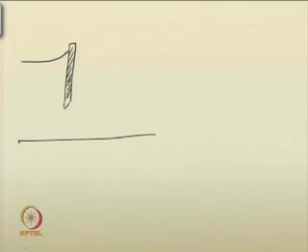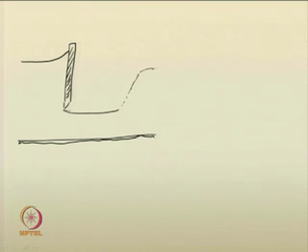Some of the diagrammatic things which we can suggest: say a sluice gate looks like this. I can just give a section. So, this is the upstream portion, and in the downstream this is the channel bed. Water gushes like this. So, it may form a hydraulic jump, we are not sure. This is the upstream depth y 1.